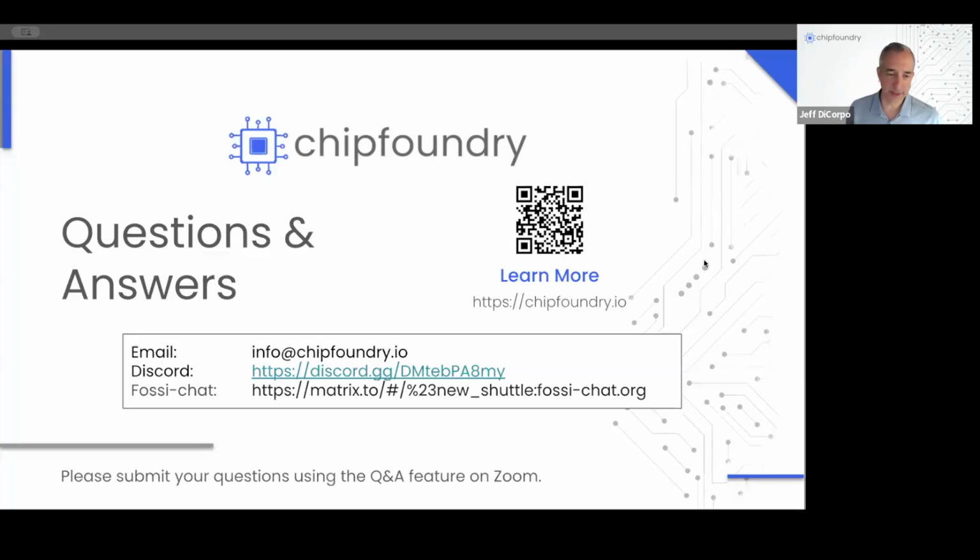Exactly. But the template does come with, as Marwan mentioned, timing constraints that have a budget associated with the Caravelle. So for all the signaling that goes back and forth to Caravelle, that's already predefined for you, and if you utilize those constraints, you'll ensure that you get good timing closure for your macro within the overall chip.